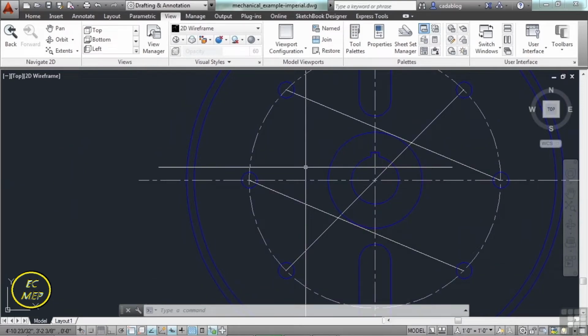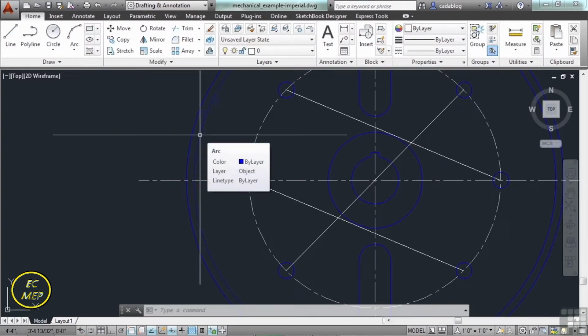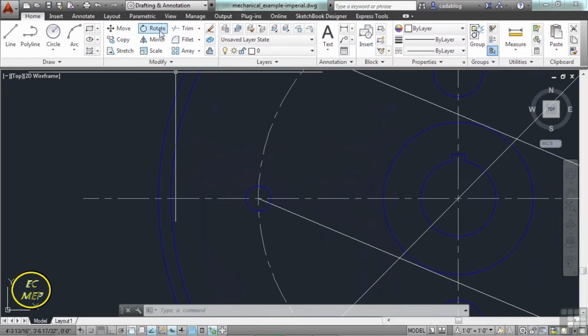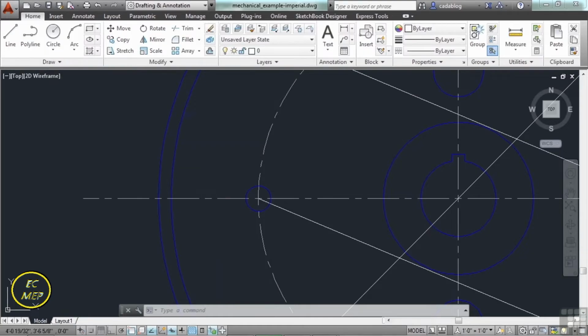Again, you may never need to, but if you do and you want to enter everything that way, because let's say you only have a 2-button mouse or the scroll wheel isn't working for whatever reason, and you still need to work, starting your command, then going to the View tab on the ribbon, picking Pan or picking Zoom, can be difficult. It takes more steps. You don't want to use more steps. You just want to work. So apostrophe Z or apostrophe P for your transparent commands.